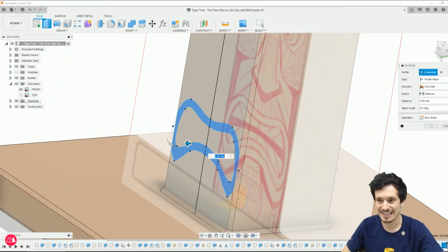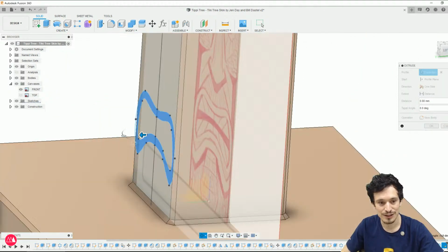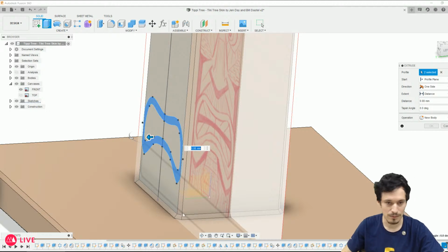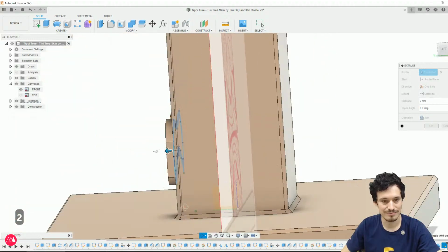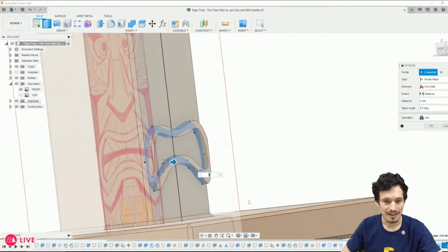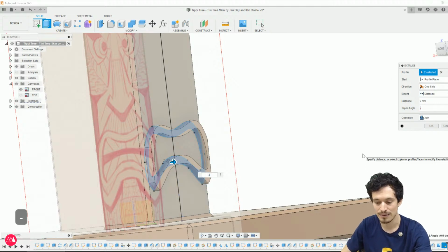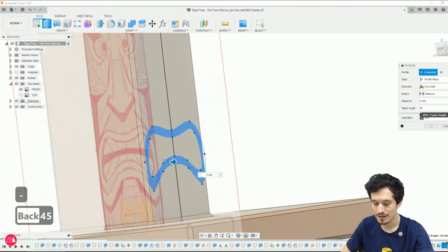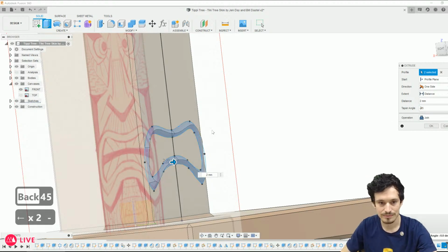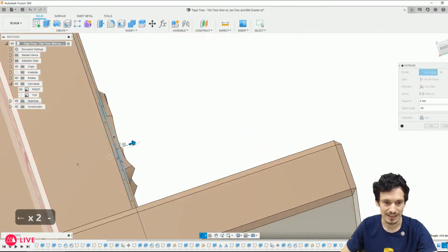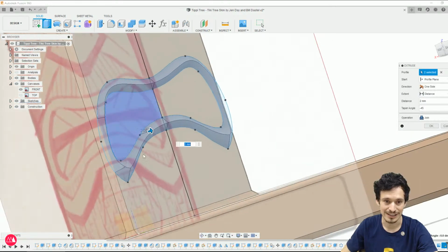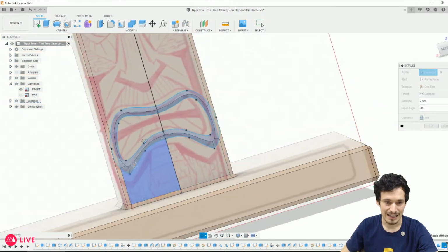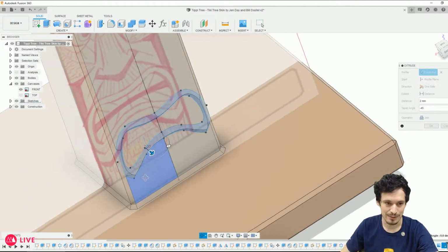All right, so I hit E for extrude, and we're extruding from that face. I want it to pop out, maybe 2 millimeters. Let's try that out. Looks like a good distance for the lip. Like I said, this overhang will not fly, so one thing I can try is to put the taper in right now, say 45. No, let's say minus 45. That actually works in an interesting way. It gives us this pointy surface. That's kind of cool, actually. I didn't mean to do that, but I might stick with it.